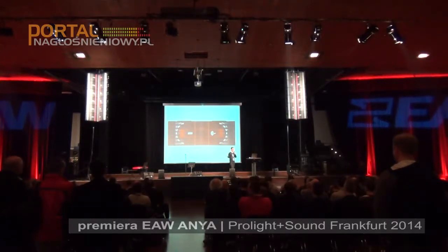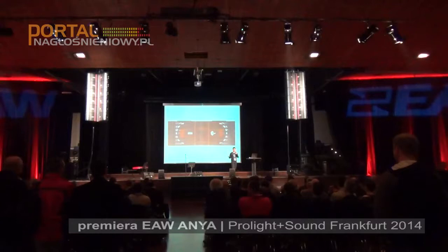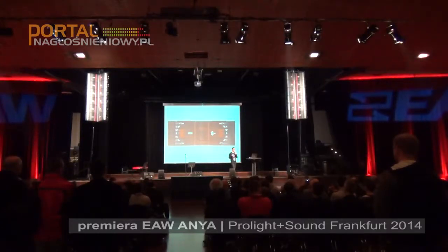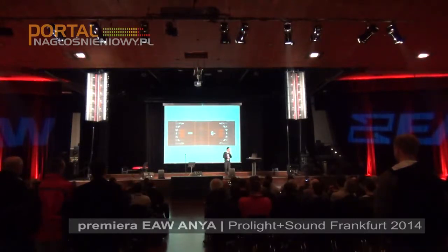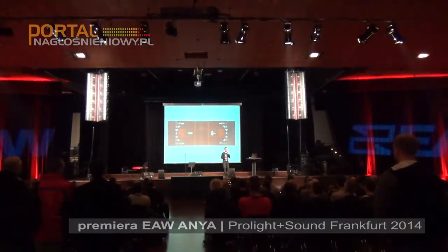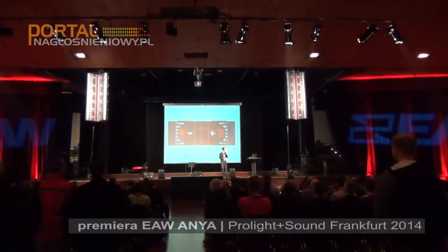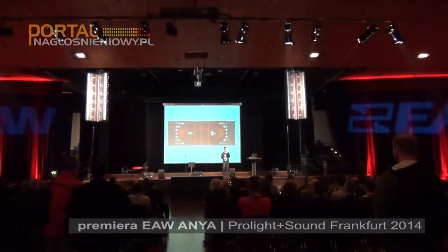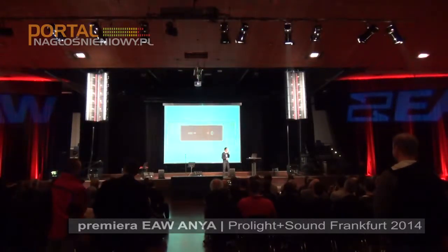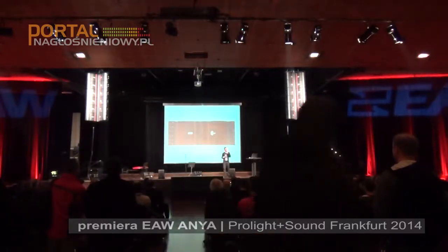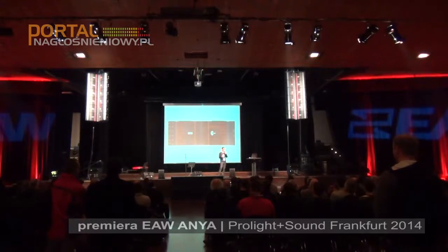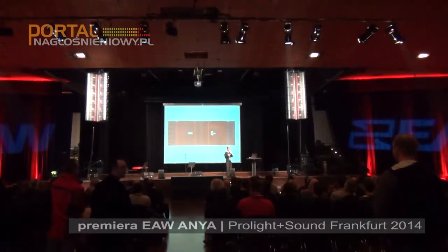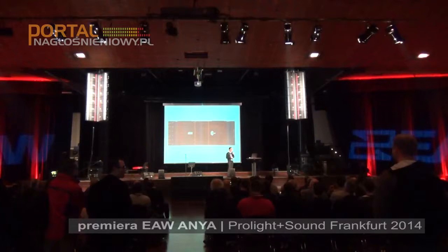So we have an extreme extension of beam width into the lowest operating range of that 15 device that perfectly complements what we're receiving from the mid and the highs. But putting those low frequency apertures right in the middle of our large mid and high frequency horn didn't mean good things for the mid and high frequency sections themselves. So we went on to fill each one of those low frequency apertures with a formed grill that ensured a smooth and continuous horn surface for that mid and high frequency wavefront.